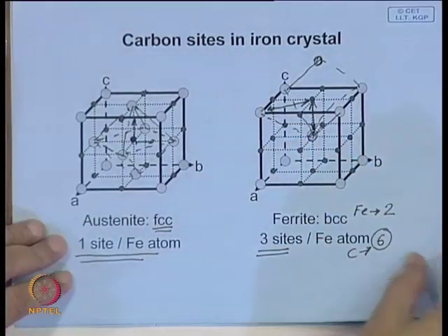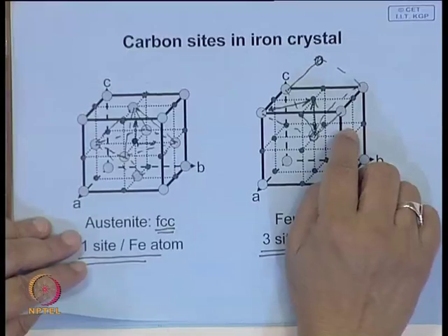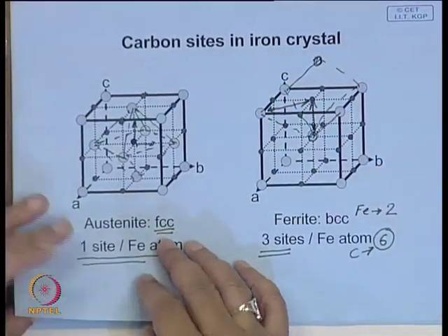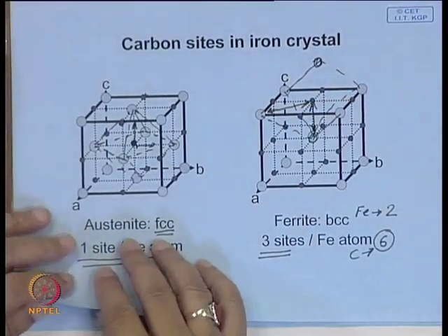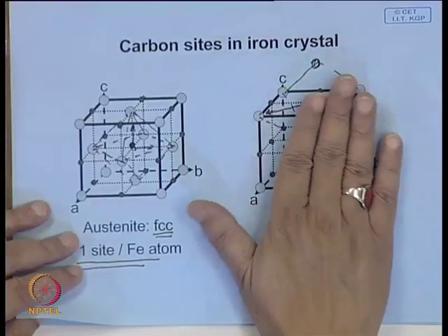which has a much stronger stress field than this. It is not only hydrostatic, it will also have a shear stress field. So, therefore, these types of stress fields can block the dislocation motion much more effectively.